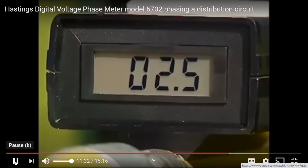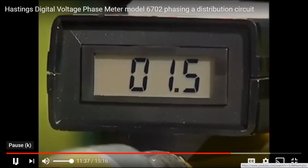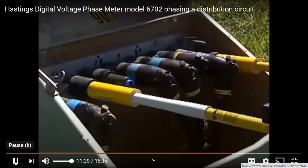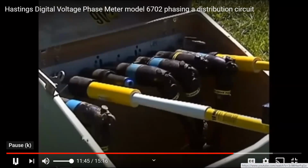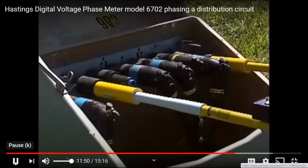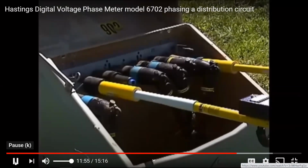And the only other one, which happens extremely rarely, is where we have a burnt open and real dry conditions or sand, and it accepts the DC charge, but you have a cable that's burnt open. You have a faulted cable and it's showing as good. What you might want to do is go to the next cabinet and put your URD grounds on that cable that you're testing, and then come over and high pot it again. If you don't see the line to ground, full current flow, it's in fact open. So you have an open cable, and that's the exception. Okay.